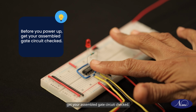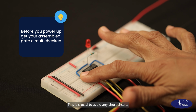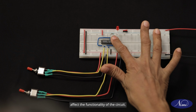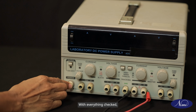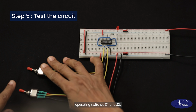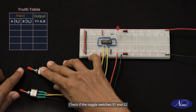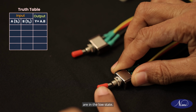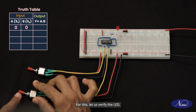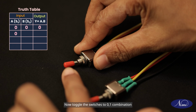Before you power up, get your assembled gate circuit checked. This is crucial to avoid any short circuits or incorrect connections that could damage the IC or affect the functionality of the circuit. With everything checked, switch on the 5-volt DC supply. Begin the test by operating switches S1 and S2. Check if the toggle switches S1 and S2 are in the low state. This indicates 0-0 combination. For this, let us verify the LED. It is not glowing. Now toggle the switches to 0-1 combination.